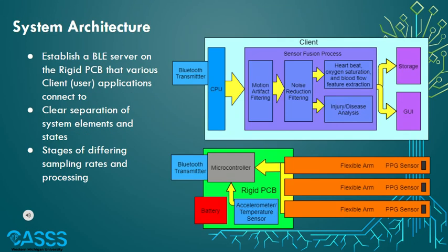The system architecture we implemented was a server-client relationship, where our main wearable PCB board acts as a server with the microcontroller hosting that server, and with clients being a mobile application, a website, or various devices, connecting to the microcontroller-based server, subscribing and listening to changes that it posts. The reason we chose that was that it was very easy to distinguish states and allow the microcontroller to control what it posts and notifies to the client.